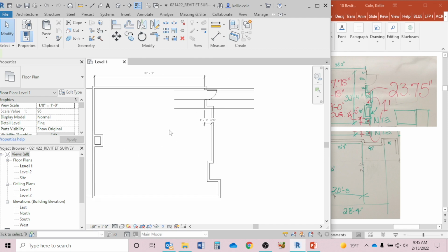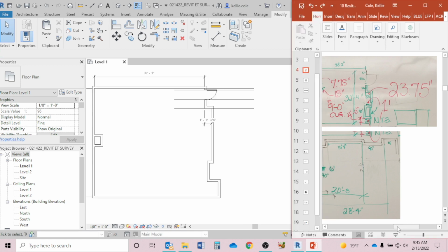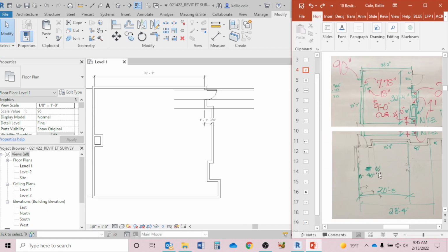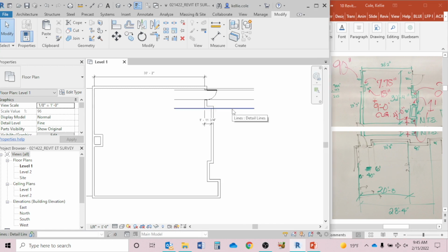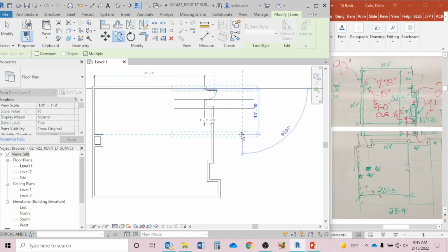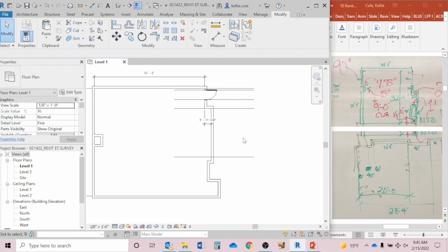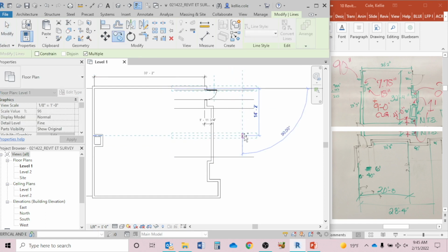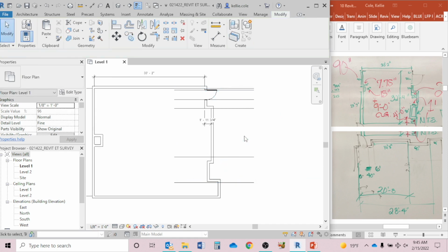Okay. I'm going to continue offsetting my running dimension along the right side of the wall. So I've gotten up to 6 feet with that line. Let's put 2 more in, 20'8" and 28'4". Go to your original line, CO, touch the line, make sure your cursor is perpendicular, 20 feet 8 inches. Escape, escape. Original line, CO, grab, move down, 28 feet 4. Good. Now let's align that shaft.